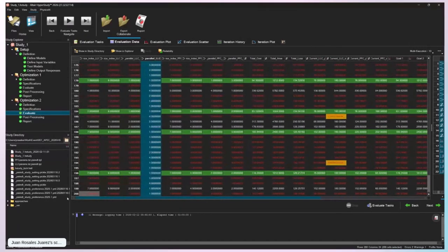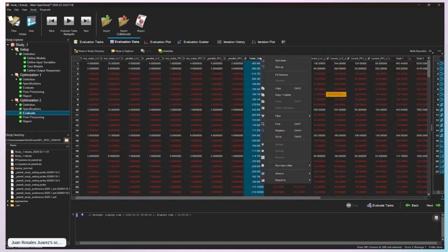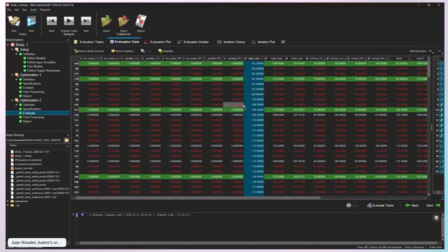And so here's where we can start looking at trade-offs, for instance. So here we have the total cost, and we can sort the results for cost. So the lowest cost is this setup. So we have device number 7, we have device number 9. We have a single device in these positions. And then for the PFC, we have these two devices. We have one device just for the fast leg and two devices for the slow leg, which makes sense that it is the most efficient in cost, right?